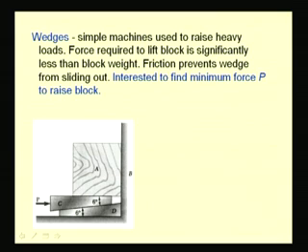So, let us now consider this wedge C, which is being pushed by the human by this force P in order to raise this load or to keep this load in this position. Since the wedge tends to move in the direction from left to right, the frictional forces on these surfaces will oppose this motion, thus they will be acting from right to left.